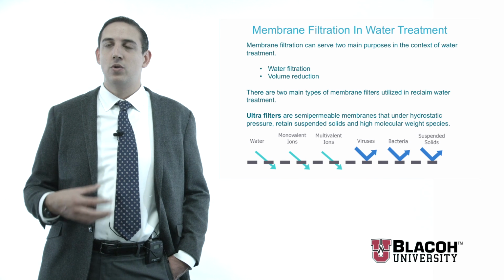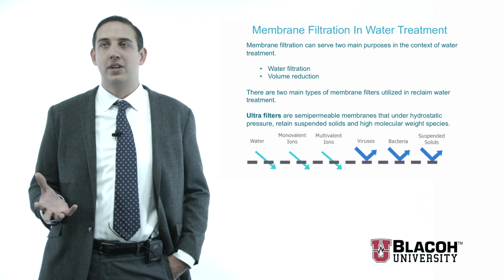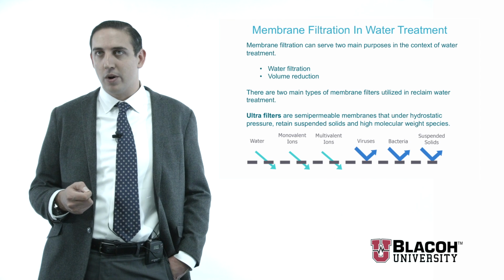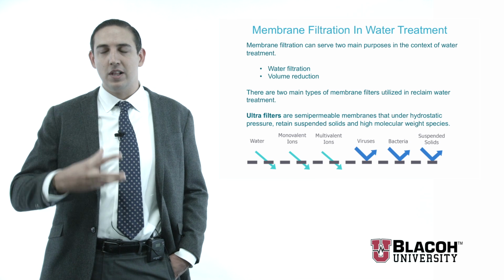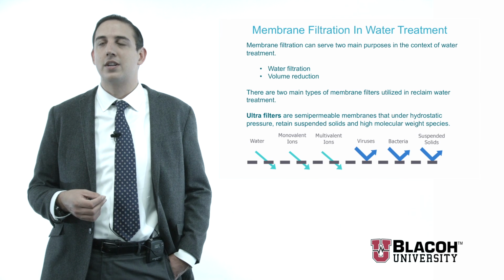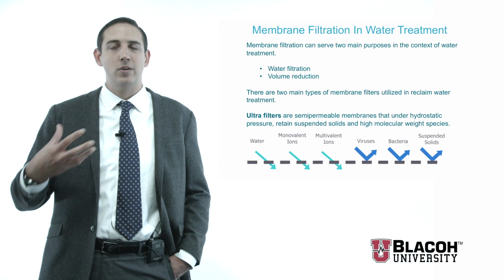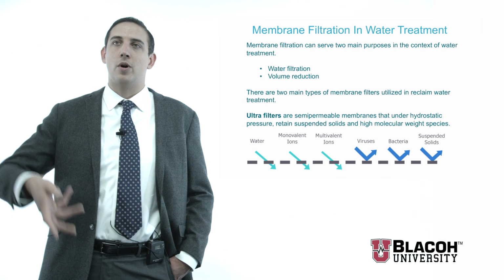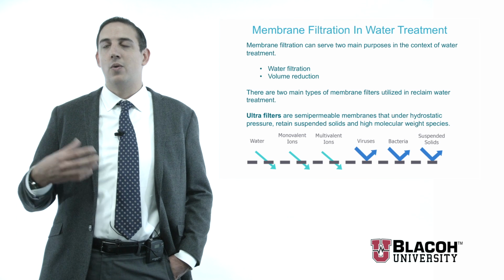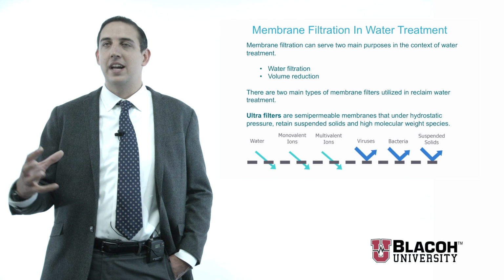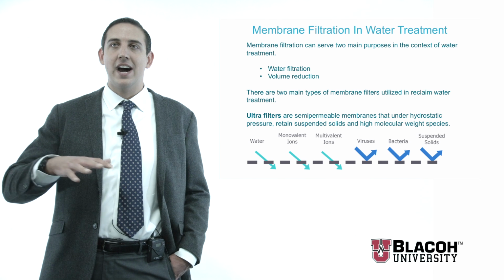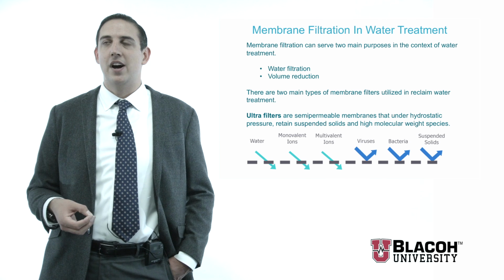In the context of cooling towers and even some rainwater applications, people do use membrane. It's also very commonly used in groundwater treatment. One of the things that's coming up a lot more now is reclaiming groundwater. For a long time, people who were putting in buildings and foundations were just allowed to pump all the displaced groundwater right to drain. Now a lot of municipalities are requiring them to reuse that water, and that water is going to have very high mineral content, because it's not like well water, it's very high level subsurface groundwater.